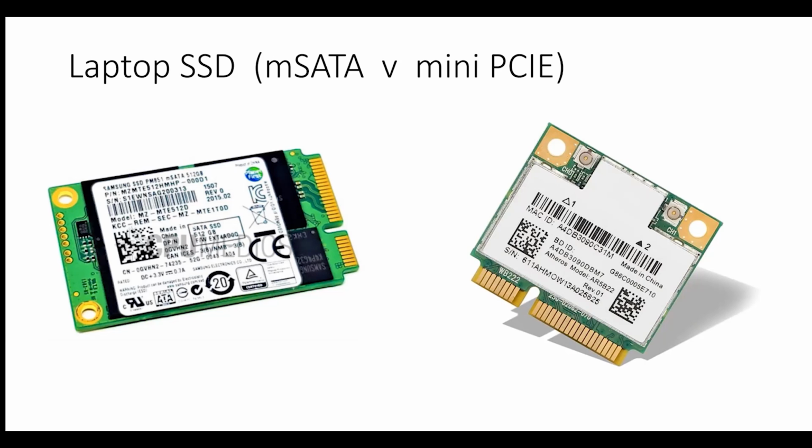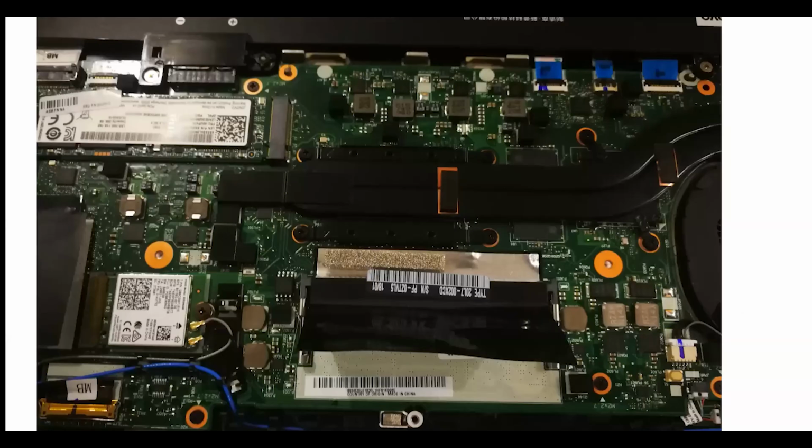The thing about these is the sockets are the same, but they won't work in each other's. If I plug the radios in where the hard disk should go, it won't work. If I plug the hard disk in where the radios should go, it won't work. So you can't get these wrong. Luckily, they're being phased out. They're not as popular as they were, which is good news because it's a source of confusion. But you may open my laptop, you may open my computer and find these, and you really have to know about them. Here's a Lenovo laptop with the back off, and it's got both of these.